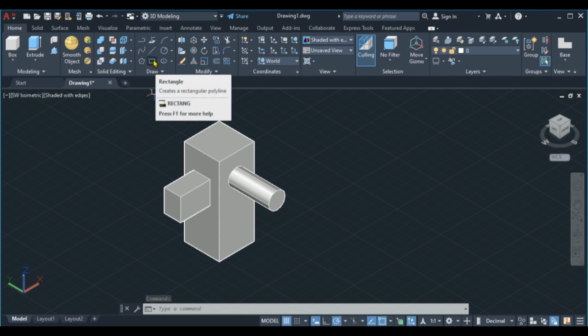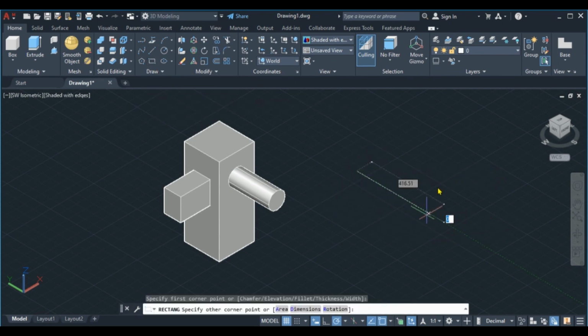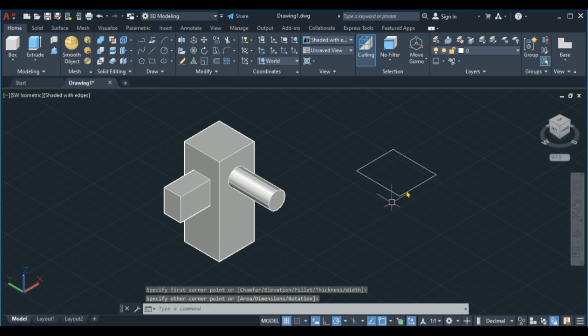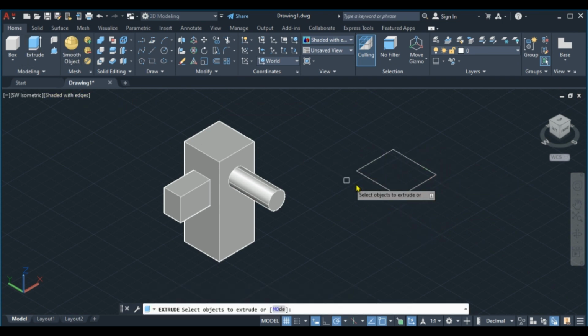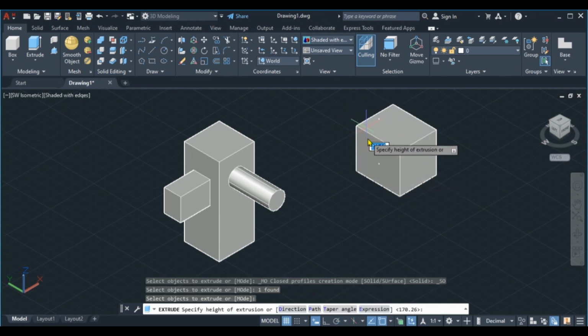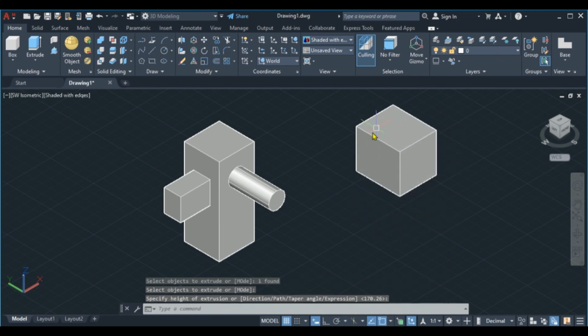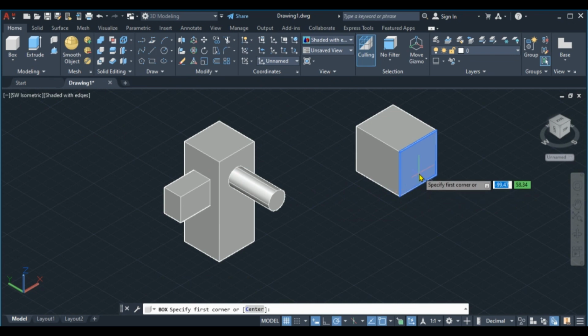Now, for example, let's say I have this rectangle here, okay, I have this nice rectangle here. I can extrude it by selecting the extrude, click on the line, press enter on the keyboard, and I'm able to extrude either in a positive y-axis or in a negative y-axis. So let's try and go back to the box and see how we can incorporate the box with this one.